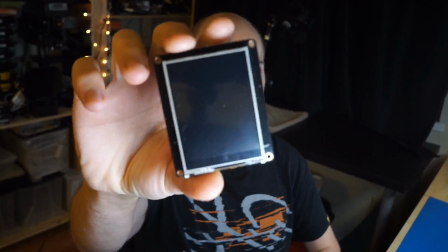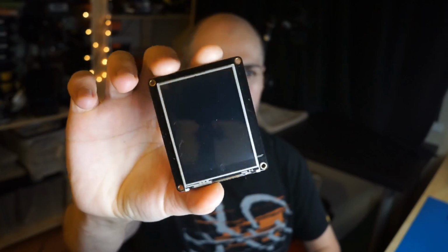Hey, it's Tony from Adafruit, and in this video we're going to look at how to draw shapes and graphics on pixel-based displays with MicroPython. In the previous video I showed how to use the ILI9341 TFT LCD display, just a tiny little feather wing shield that gives you a nice little LCD. There's a 320 by 240 pixel display on here that you can draw pixels on. But the problem is you can only draw pixels, which gets a little bit boring.